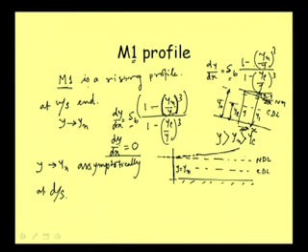So, normally the flow cannot rise or go beyond the normal depth line. There must be some obstruction or barrier or something which has caused the water to rise. So it is rising like that, and then when it crosses this barrier, it will definitely fall on the downstream side.